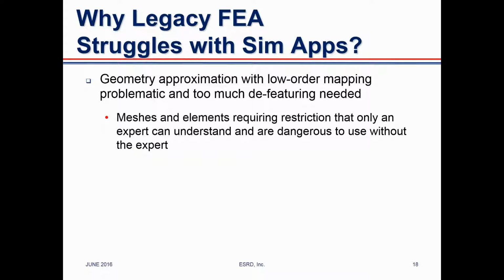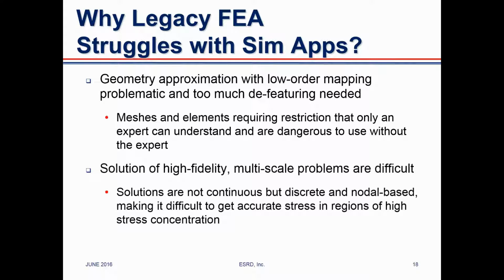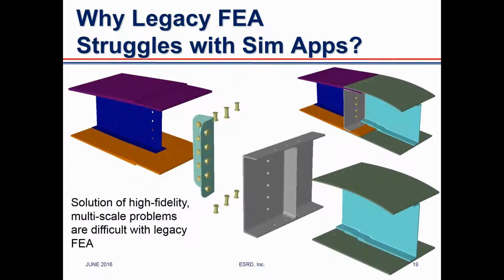Meshes and elements many times require restrictions that only an expert can understand and are dangerous to use without the expert. And the solution of high-fidelity multi-scale problems is complicated. The solutions are not continuous but discrete, nodal-based, making it difficult to get accurate stresses in regions of high-stress concentrations.